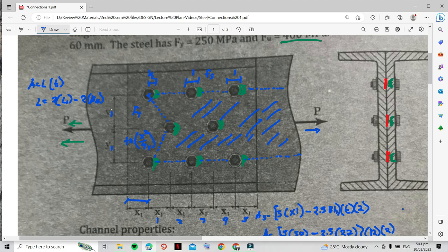Okay, and then you must add because there are staggered failures happening. So plus, there are two diagonals. This is 1 and then 2, so you need to multiply by 2. Okay, we're going to continue this part. Wait, let me just erase this. Plus 2 of this formula. The n signifies 2, and the x is x1. So x1 is 50. So that's 50 squared over 4y, which is 60. Okay, so that's the length.